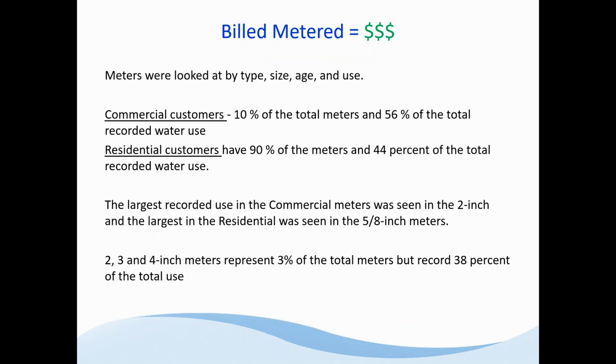In this audit, we looked at meters by type, size, age, and use, and the commercial customers represented 10% of the total number of meters, but 56% of the total water used. Obviously, the residential side was 90% of the meters, but they represented 44% of the water used. The largest recorded use in the commercial meters was seen in a 2-inch, and the largest residential was in a 5/8-inch meter. So it just isn't always based on the size of the water meter.